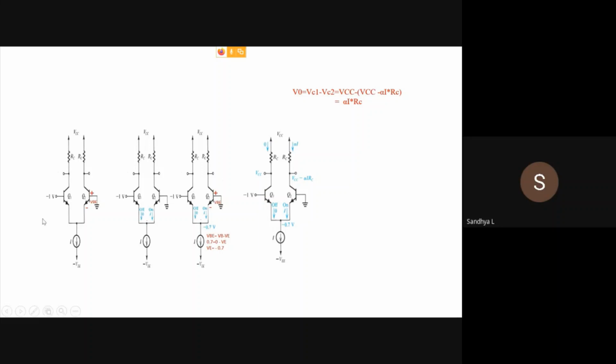So here by this particular case, we prove that each individual base voltage needn't be greater than 0.7 for the transistor to turn on. The only requirement is that the modulus of the difference between the two input voltages should be sufficiently large.